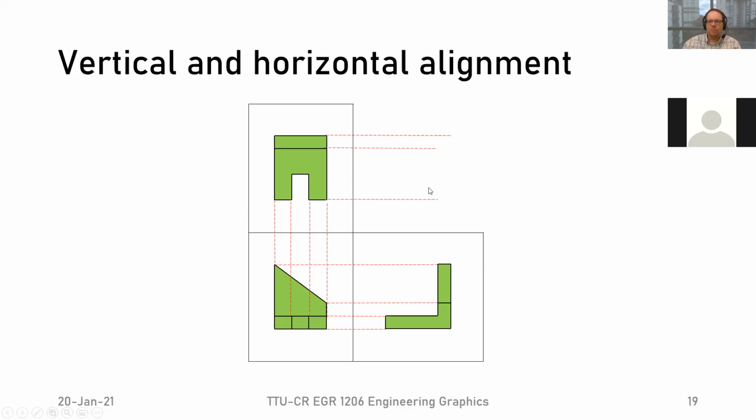So what we can do, because these are all right angles, is draw a 45-degree angle line right through here, through that open space where a fourth box would go, and 45 degrees because these are all orthogonal to each other, so half of that is 45. And then anywhere where our straight lines hit this 45-degree angle line, we drop a line that goes straight down. So we'd have these three lines go down, and you can see they all line up.